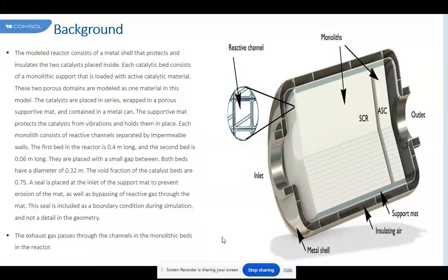There were only minor effects on the temperature distribution despite the differences in the effective thermal conductivity and rate of conversion between the core and ring. However, the cases analyzed considered the steady-state regime and with the reactants fairly diluted in the feed. Significant effects may appear in the transient operation or if the reactants are sufficiently concentrated to produce a significant release of heat from the chemical reactions. Those situations should be investigated.